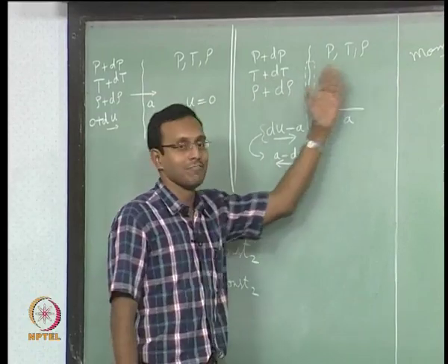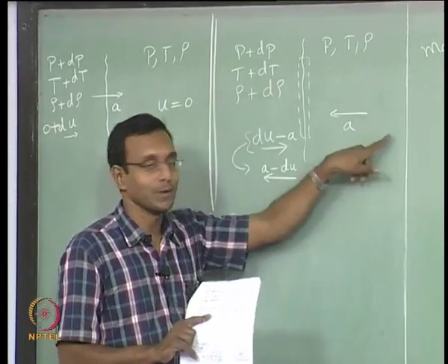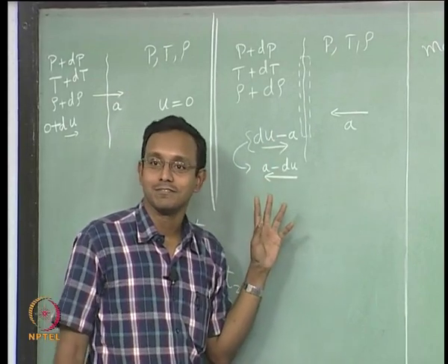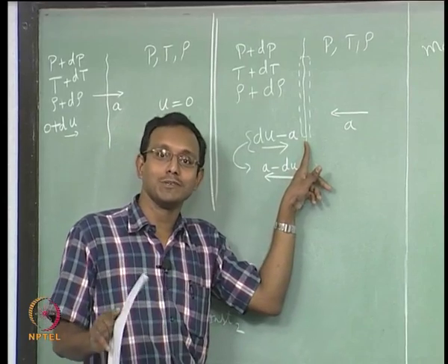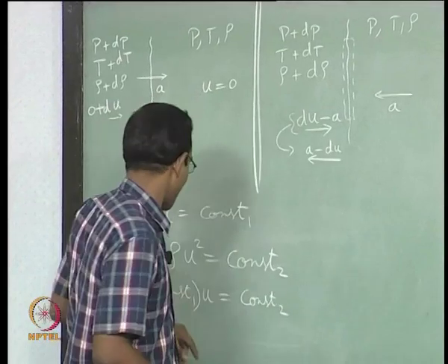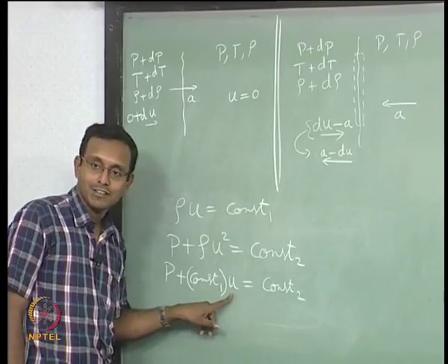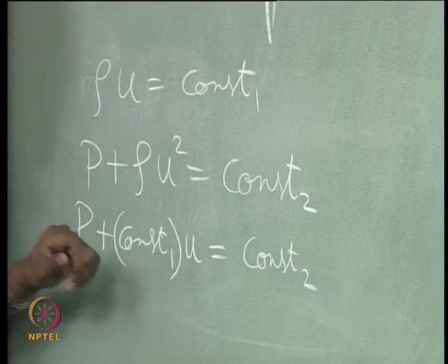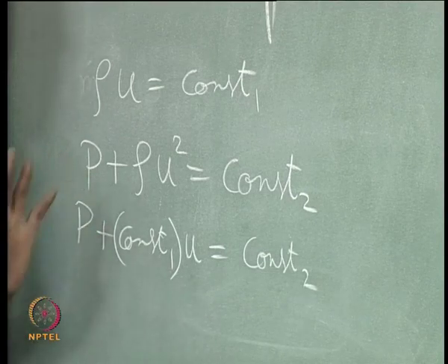The wave is going this way, information that there is too much crowd here, that is pressure is higher here, is transferred this way with respect to the fluid, but with respect to the wave is just sitting here, okay. We have reference frame on the wave now, just so I can use steady equations, that is what I have done till now, okay. And I can now use this expression to tell that compression wave velocity decreases, and if I think about expansion wave, then velocity will increase. Why? Pressure dropped, velocity should increase, okay. Different ways of looking at things.